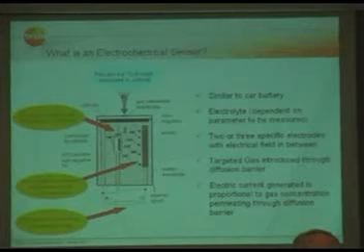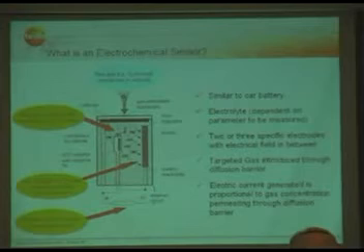This is just a chemical reaction taking place, but depending on the O2 concentration in this case, the gas concentration is proportional to the movement of the ions to the anode.